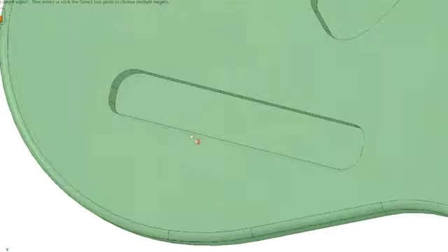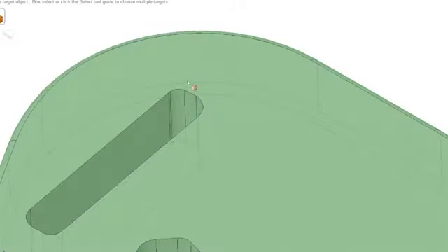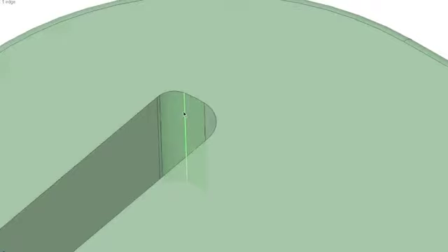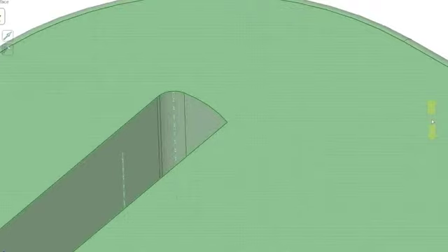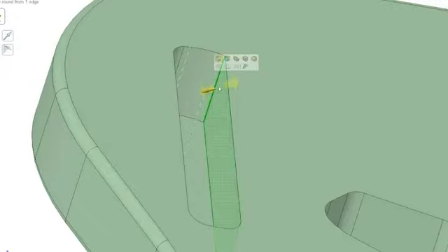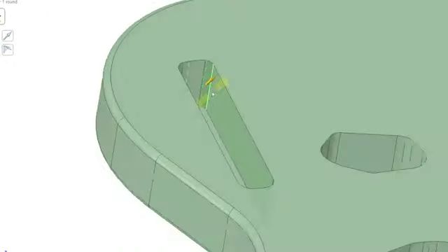One really nice thing about this is you can see I have some different fillet radius on this pocket on screen. If I zoom in here, if I want to remove those fillets, I can grab the pull command and just drag it and remove that fillet. If I want to come back in and apply it again, I can drag it and enter in a dimension. So you can say 5. Maybe I want to use a 5 millimeter radius there.